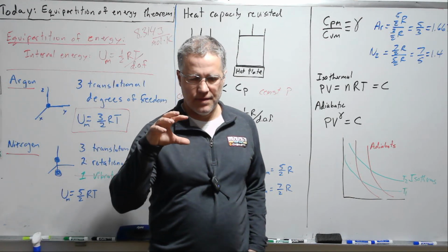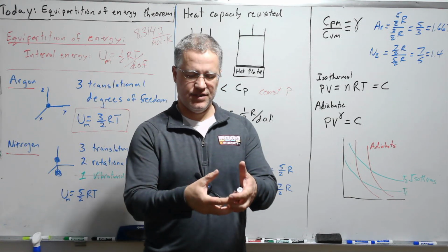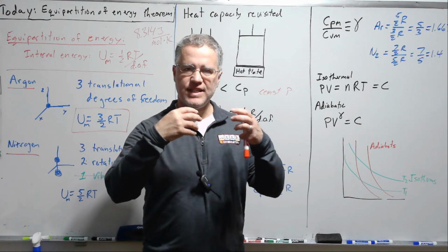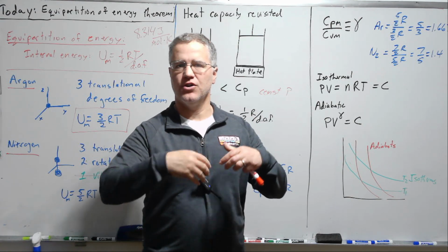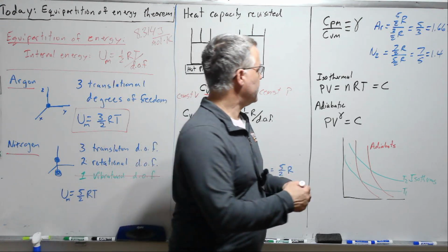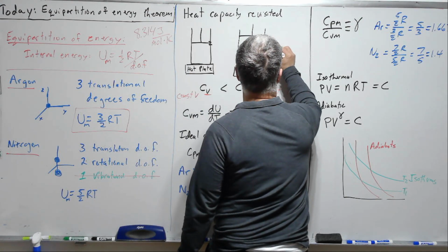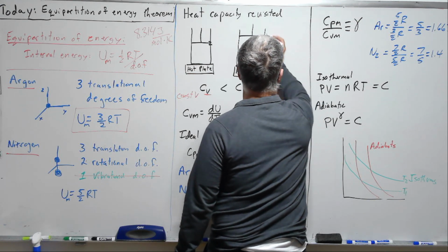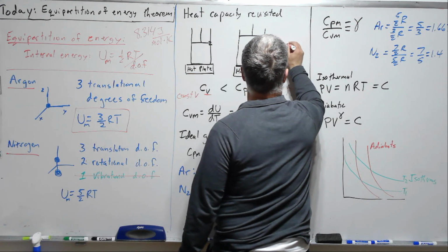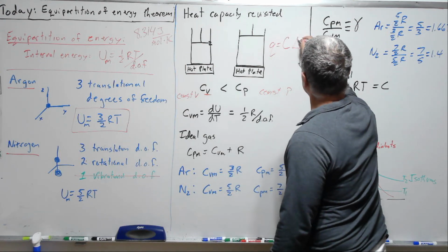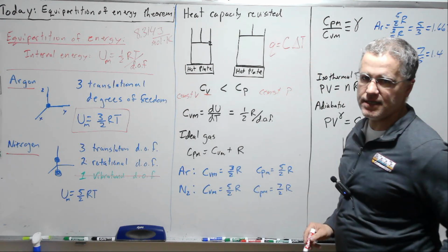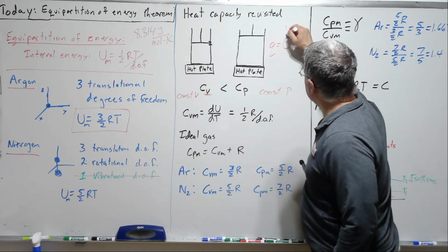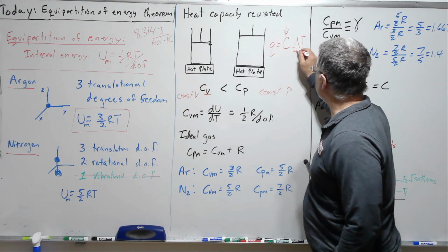So the definition of heat capacity is the system's ability to resist a change in temperature when we add heat energy. So we know that Q equals C delta T, right? C delta T. And so we're dumping heat in. We're looking at a temperature change. Right?